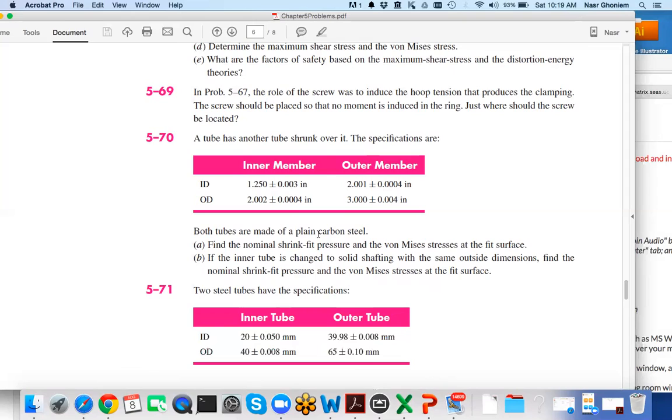When we attach, we weaken the shaft. We might have to mill the shaft and put in a spline, or we have many different types of attachments, each with its own pros and cons. One easy solution is the press fit, in which the inner shaft is made deliberately a little larger in radius than the flywheel's inner radius.